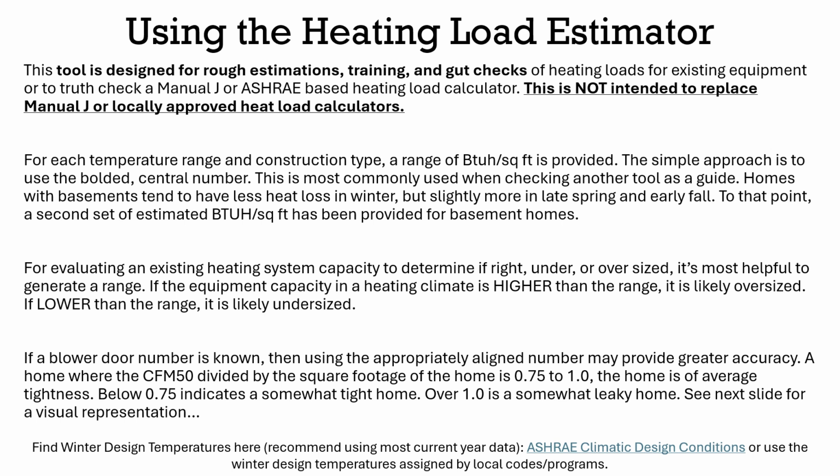You can see the very first thing it says is this is designed for rough estimations, for training, and for doing gut checks. By doing gut checks, I may mean if I'm a technician who goes out to a house and there's a no heat, no cool call, and I recognize that we can't save this equipment, I need to have a salesperson come out and size it. I could use this as a very quick way to say, hey boss, we need a salesperson down here, and I think this system is oversized, and here's why. That's a good use of this tool.